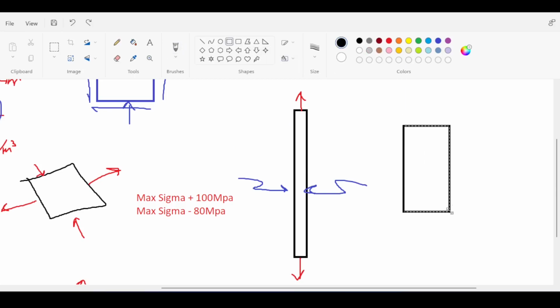Allow me to remind you of something in soil mechanics. In soil mechanics, you had the triaxial test, where you had a soil specimen under axial force, compression, and under hydrostatic pressure on its sides. And you know that the hydrostatic pressure had an effect on the load carrying capacity of that soil specimen. Now, I'm not going to make this become a soil mechanics lecture, but I want you to remember that the lateral pressure, the hydrostatic pressure on soil, had an effect on the soil carrying capacity.